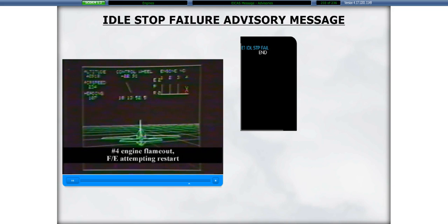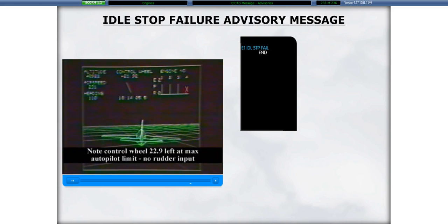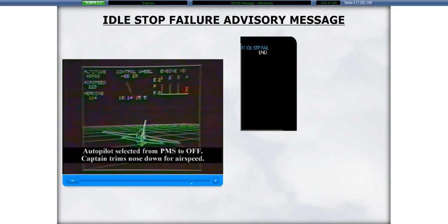The problems will most likely develop at a point during the flight when the autopilot is engaged. The autopilot will compensate for the asymmetrical thrust on its own. It takes an alert flight crew to recognize the situation that's developing. If the airplane is badly mistrimmed when the autopilot is manually disconnected, or when the autopilot reaches the limits of its authority and automatically disconnects, only seconds remain before an unusual attitude is encountered.